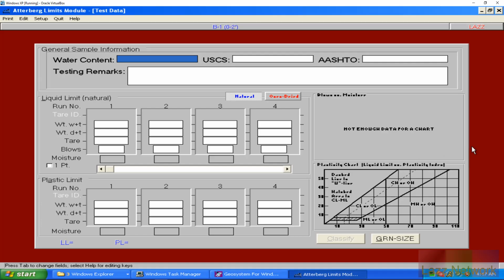So the idea is that when it comes to clays and silts, if you want the rigidity of it to be maintained, it needs to stay within a specific moisture content. And that's what this test helps determine: at its driest limit, because when you do your plastic limits, you keep doing it until it starts crumbling apart, and then you get that moisture content. And that's going to determine your plastic limit, which is PL here. And for this, it's just an average of all of your moisture contents, whatever that's going to be.